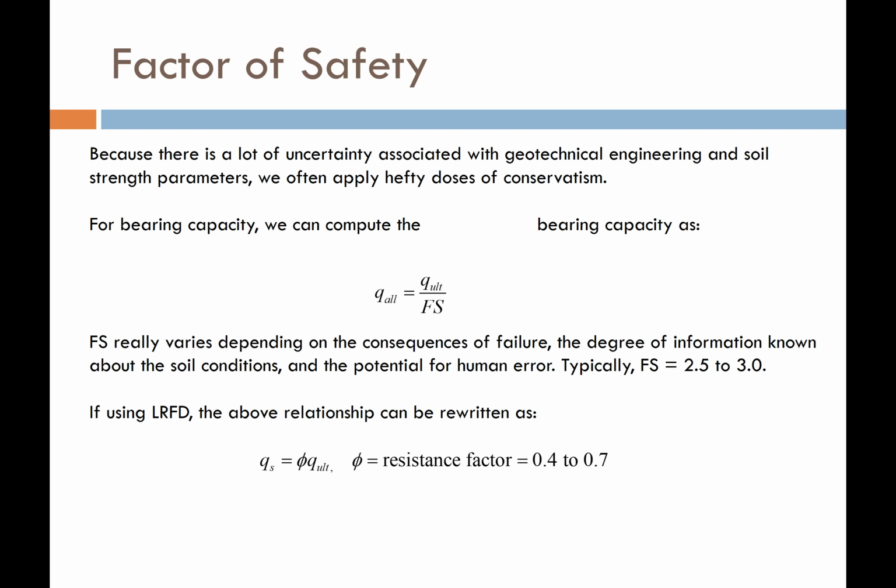Okay, we're nearing the end here, the things we want to talk about. Let's go ahead and introduce you to the idea of factors of safety with bearing capacity. Bearing capacity is something that we tend to have a lot of uncertainty with. And it totally makes sense, right? Because there's so much uncertainty whenever we deal with what's beneath the ground, because we can't see it. And we can only sample the soil in select locations, here or there, but we can't sample or know what all of the soil is.